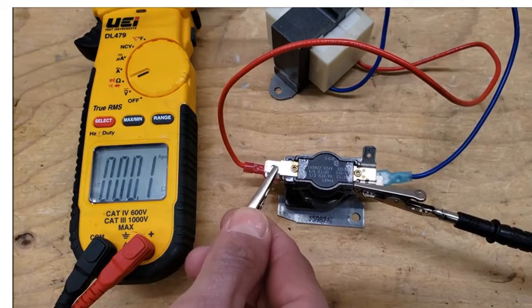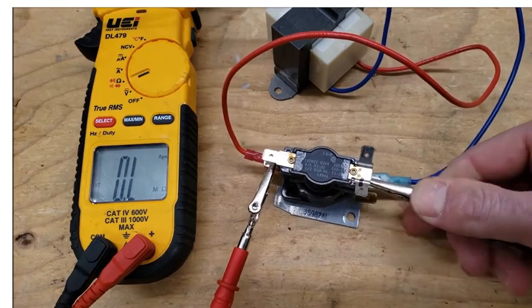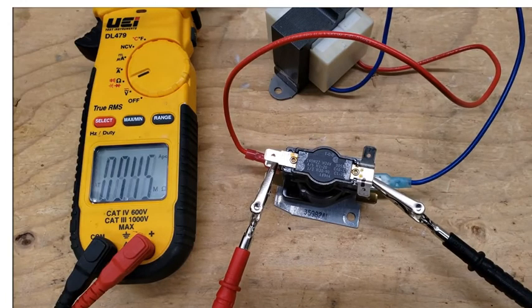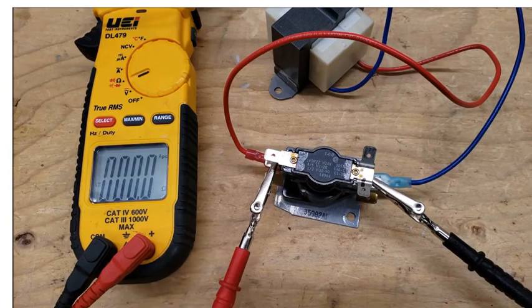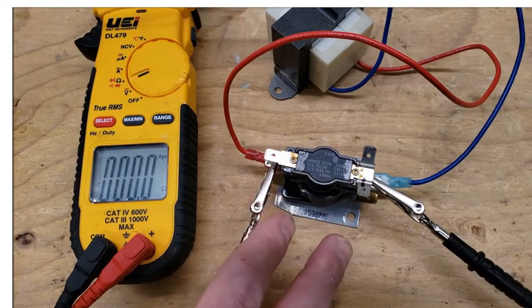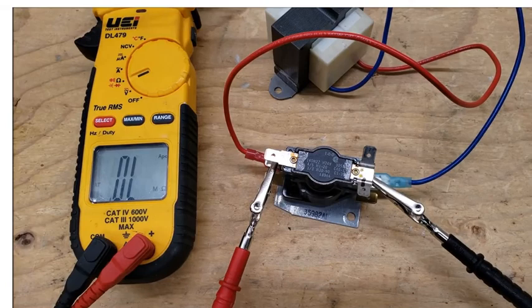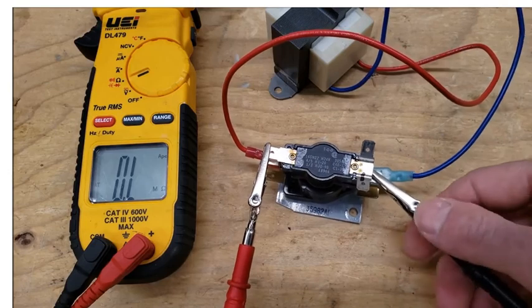Okay, so now it clicked. We're going to go ahead and move these down to the lower level. And you see that we're reading OL. So now we're reading 0.0 ohms of resistance. I'm going to go ahead and disconnect the power, and on this lower level right here between 1 and 3, it should open the electrical circuit up a lot faster than between 4 and 5 at the top. So here we go. Now we're going to go ahead and switch these because these ones are likely still going to be connected up top.